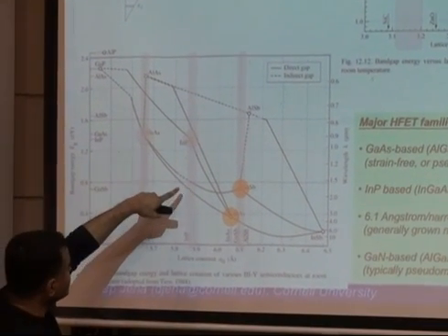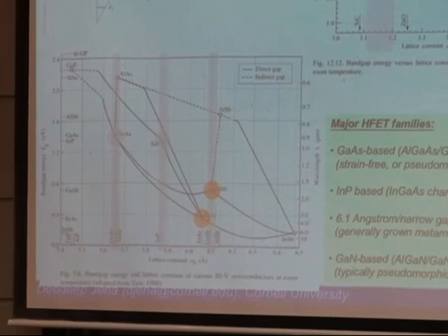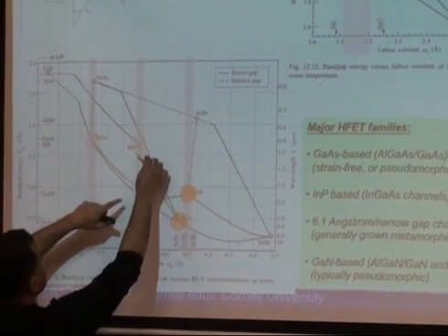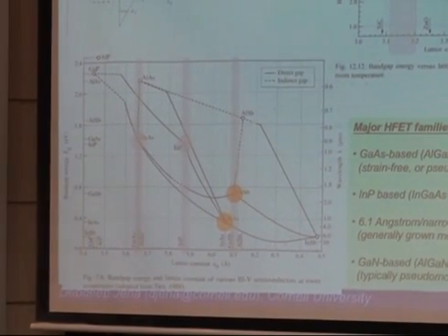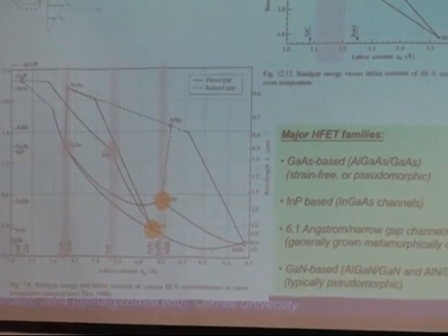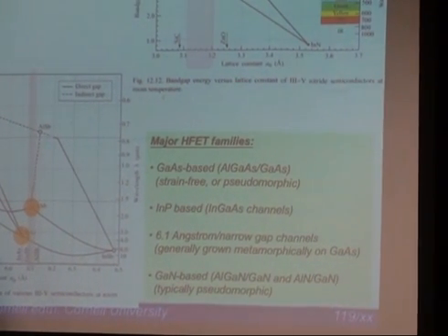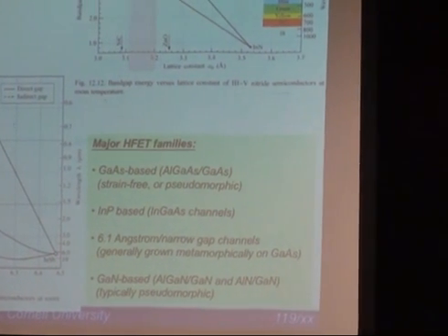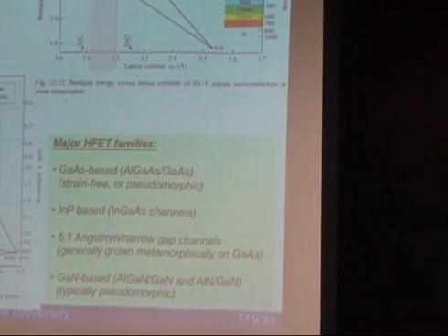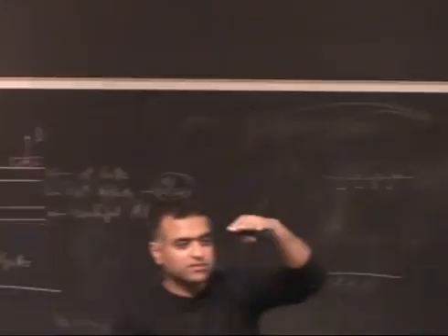And then your barriers, you can use indium phosphide, but that's rarely used. What is actually used is, you want a larger conduction band offset, which means you want a larger band gap difference between the two. Indium phosphide gives you a nice band gap difference, 1.4 minus 0.7, so about 0.7 electron volt, out of which about 70% goes to the conduction band, as we had seen.